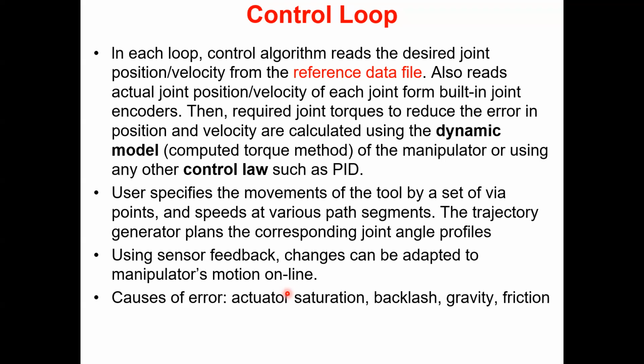And also gravity, as I explained to you previously: all the horizontal axis joints will have to cope with the nonlinear gravity problems. That can cause additional torque requirements, and it might lead to actuator saturation also, right? Certain things can be foreseen before you actually implement it, such as whether the nonlinear gravitational components cause any additional torques, which lead to actuator saturation.